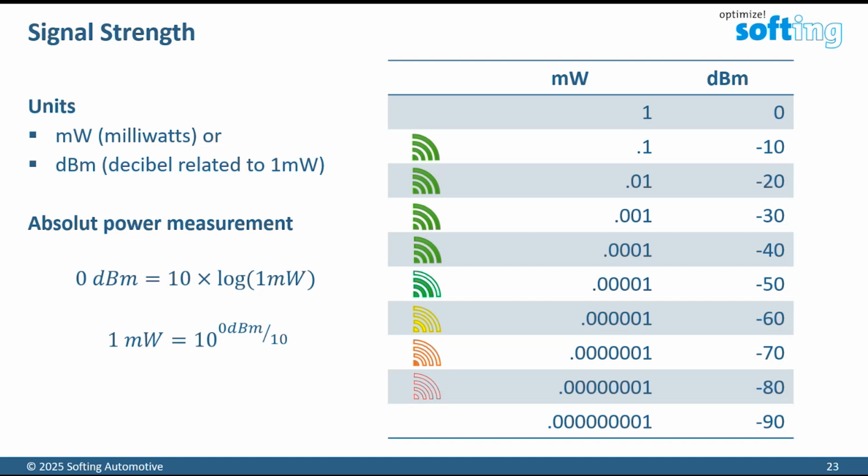And good values are still from minus 40 down to minus 72. Then for voice transmission, it's minus 62. Below minus 71 dBm, more or less you can't transmit any useful data. If you go to the noise floor, it is something like minus 92. Then it gets worse and worse, the data rates go down, and you have a lot of repetitions where it sends again. Usually fair is from minus 40 to minus 70. Minus 72 is the boundary for site surveys and so on.